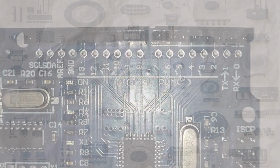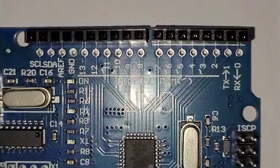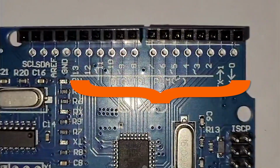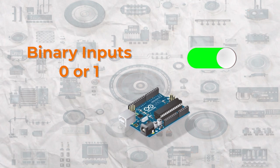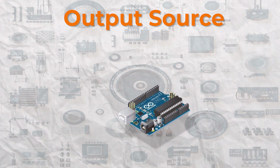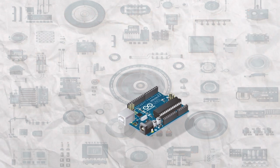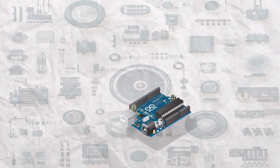So next, let's talk about the pins. On the topmost corner of the Arduino board, we have digital pins written from 0 to 13. These can read binary inputs 0 or 1, like switch off or on. They can also act as an output source. If you set it high, then it will source 5 volt, or if you set it low, then it will source 0 volt. And this will allow different components like an LED to work with it.